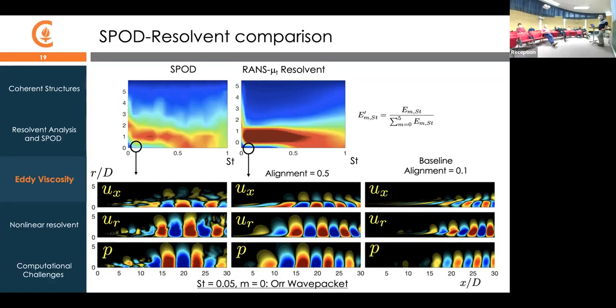It's the viscosity in the resolvent that you adjust to get the response that matches what you see in the SPOD. Well, when we tune this eddy viscosity model, we still have a resolvent calculation with the eddy viscosity, right? So we still get a set of forcing modes and a set of output modes. And we still get gains. What do you call them? The forcing modes, the columns of B, right? Oh, okay. Thank you. It's the optimal basis, an optimally amplified basis to describe a generic force.